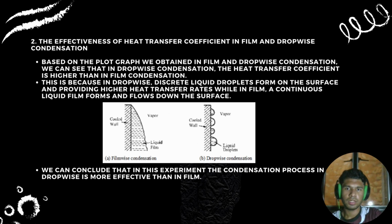Number 2. The effectiveness of the heat transfer coefficient in film and dropwise condensation. Based on the graphs we obtained, we can see that in dropwise condensation, the heat transfer coefficient is higher than in film condensation. This is because in dropwise condensation, discrete liquid droplets form on the surface, providing higher heat transfer rates, while in film condensation, a continuous liquid film forms and flows down the surface.